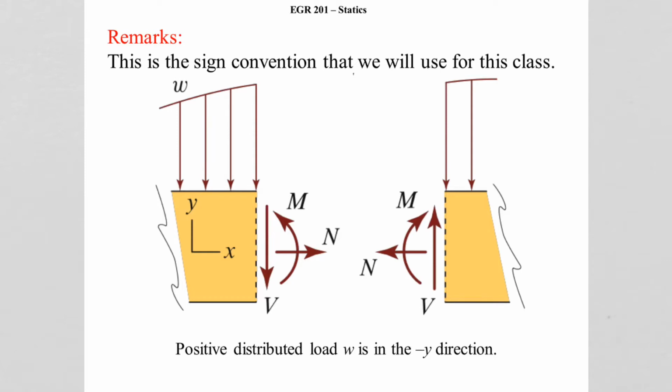So if we cut a beam with this coordinate system shown here, our shear force, again, going down on the left-hand side of the beam is considered our positive sign convention. Our shear on the right-hand side is going up. Our moment, again, is one in which we will say causes a smile in the beam on either side, so it's a positive direction for that.